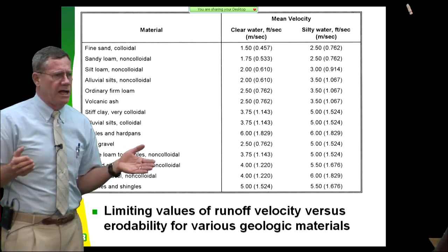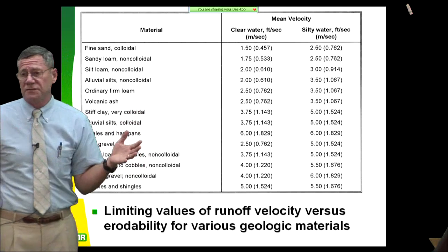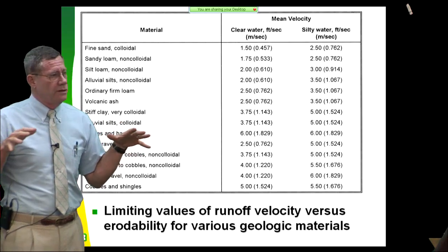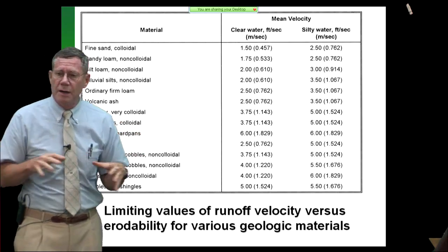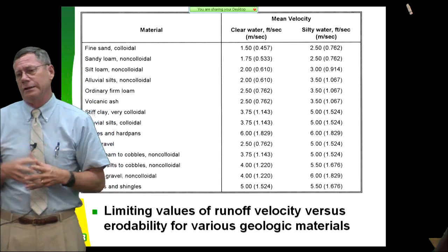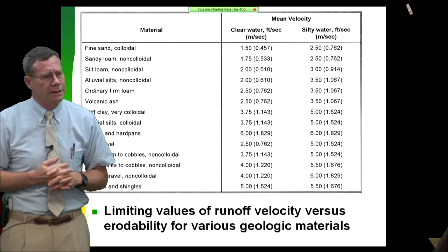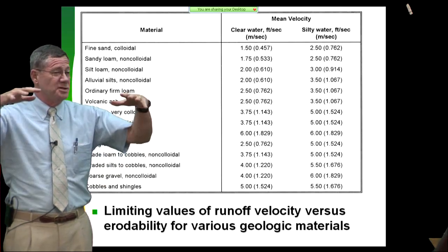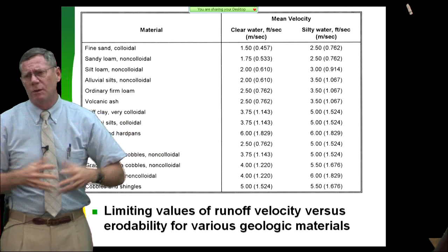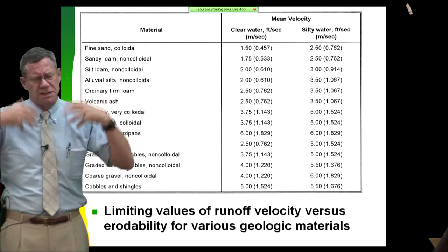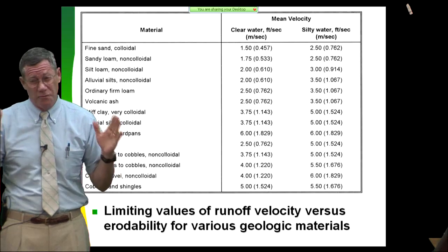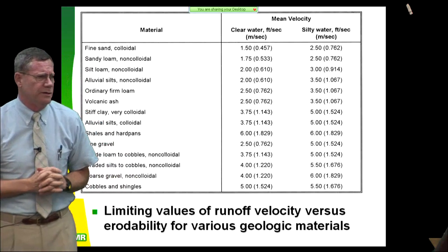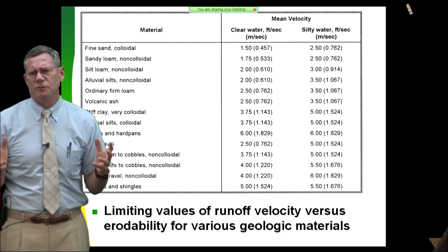When we have a landslide dam across a major river, and these are our biggest floods that we have in the world, they don't occur real often in the continental United States, but they're a very common occurrence in the Hindu Kush and down in the Andes in South America. When these things fail, no matter how big they are, some of them almost a mile high, they disappear in 12 hours. So all that material gets eroded out in 12 hours, and by 24 hours, your hydrograph is down to where it's going to be for the next few hundred years. That's how fast it erodes.